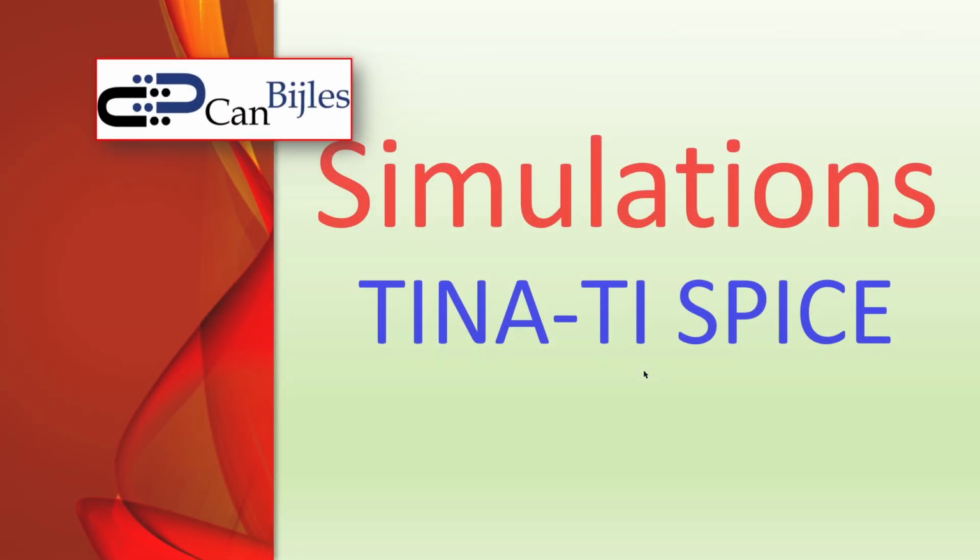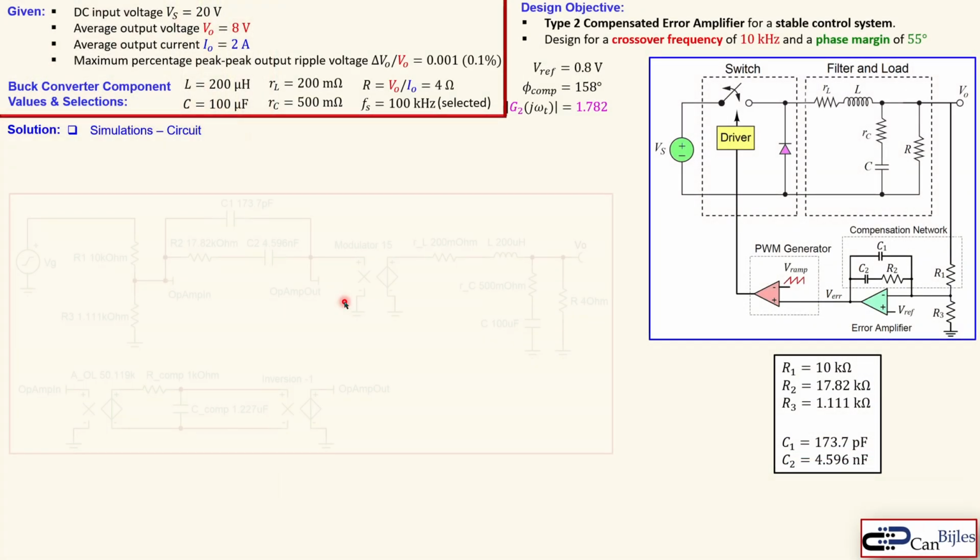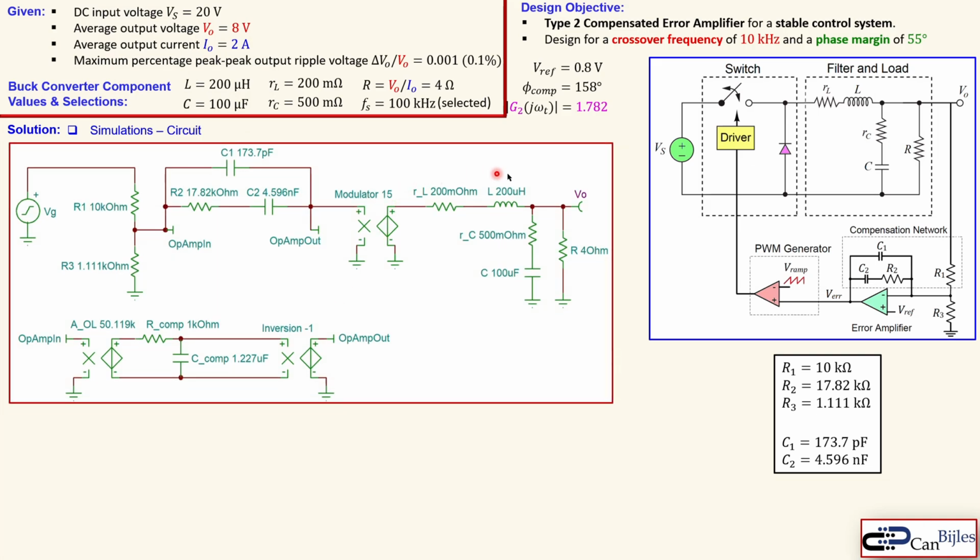Okay, now let's also look at the simulations in TINA TI Spice, but using the real circuits. So this is now the circuit in TINA TI Spice. You see here the AC model of our buck converter. You see the inductor and its ESR, the capacitor also, and our 4 ohms as the load. We have the modulator, which is the voltage controlled voltage source, with 15 as the gain. See here C1, C2, these are the values. We have also R2 here, R1 of 10 kilo ohm we have selected, and R3 we have calculated because of this reference voltage here. And this is the error amplifier.